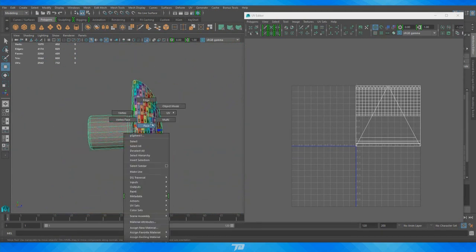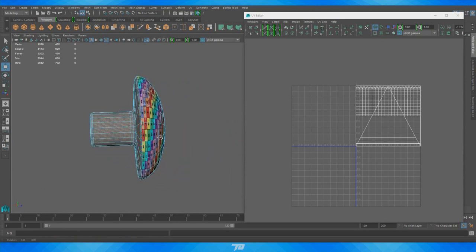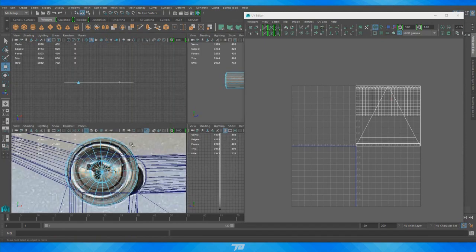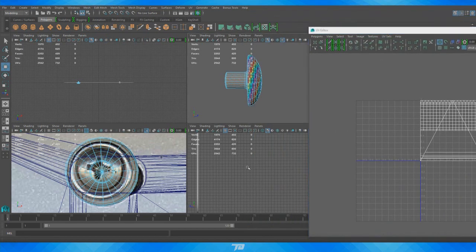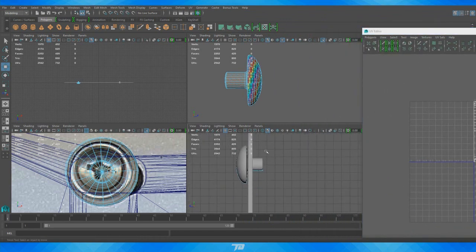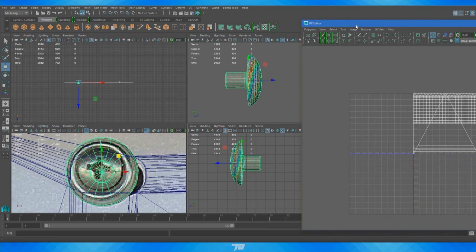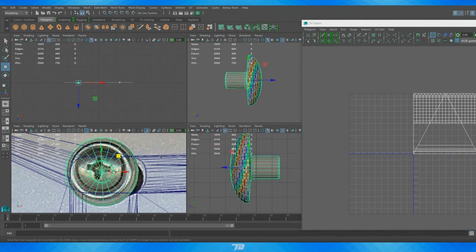And as you can see, just like the other object, this is pretty incorrect as far as mapping textures goes. So let's just select the faces and sort of do this piece by piece in a sense. So I'm going to go into our side view actually, just so it's easier to do this. And let's just move this aside for a second. Where is our bolt? Do I have this isolated? Oh, no, I don't. Here we go. So let's select this bolt and isolate it. And the only reason I'm going to the side view for now is just so I can get a perfect selection of these front faces.